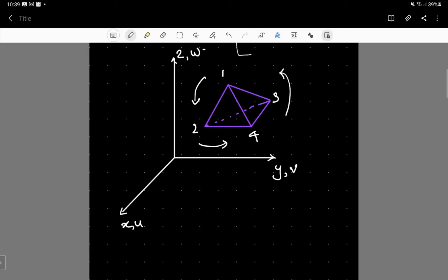So hope you can remember, we used the same protocol when we dealt with the constant strain triangular element, where we used a counterclockwise numbering method. Once we do away with the numbering, of course, this is only important when we are deriving the matrix in the global coordinate system.